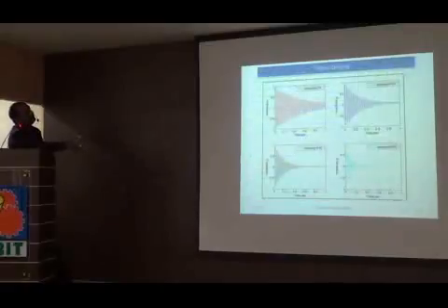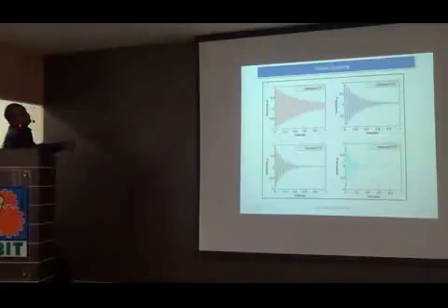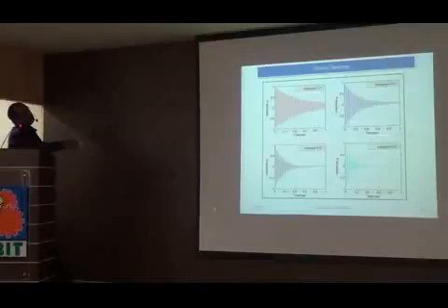One of the important factors required in fixture design or fabrication is that it needs to have very good damping. What is damping? Damping is an energy dissipating mechanism. For example, if you have good damping, assuming it is underdamped viscous damping, what we mean is it comes to the initial position very quickly. For example, you can see here, compared to this, this has come to the initial position quickly. That means this has more damping.